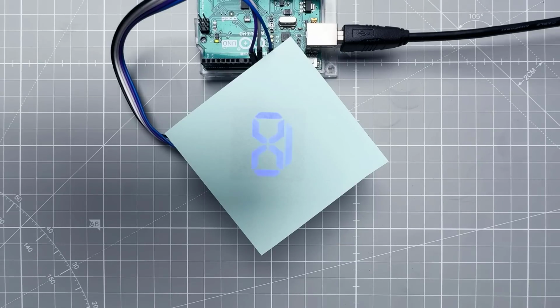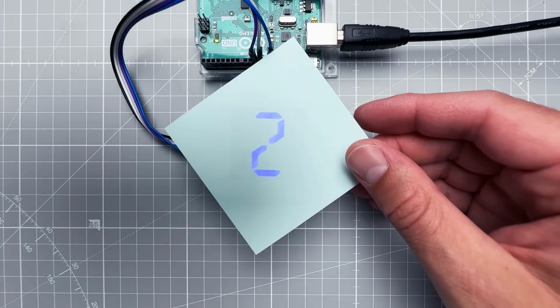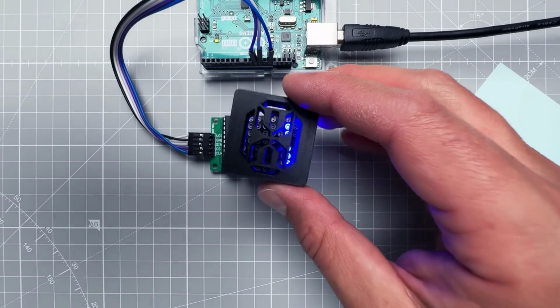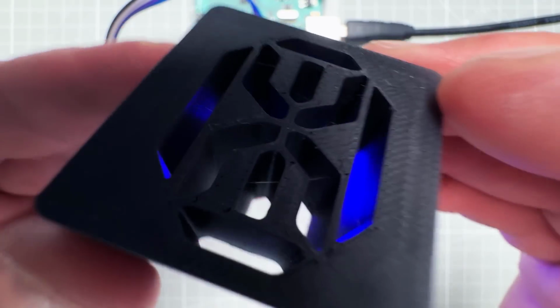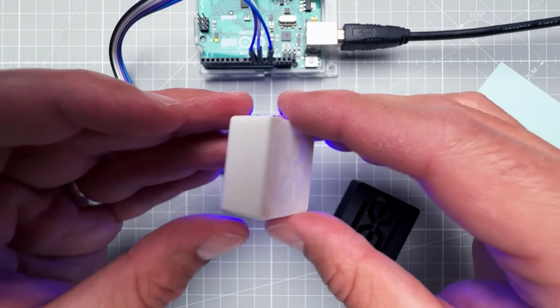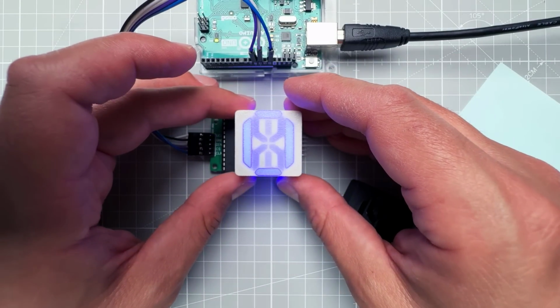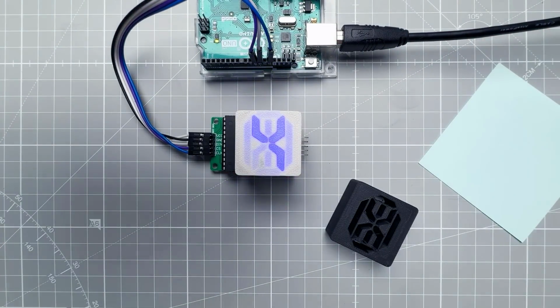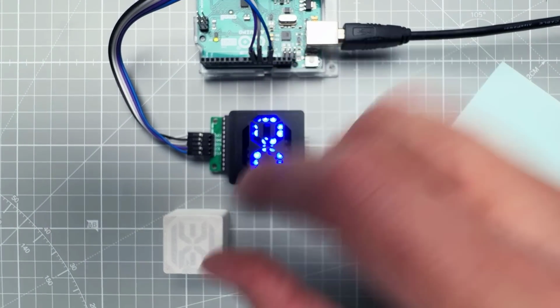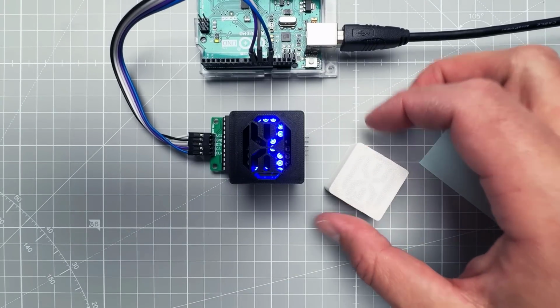That filament is slightly translucent, so if we only print one layer, it should be transparent enough to act like a diffuser. By the way, the reason why we don't print everything in the white PLA material is exactly the same. The walls between those segments are quite thin, so some light might be bleeding between those segments if we use the white PLA. You can see that with the white 3D print, even the segments which shouldn't be lit are slightly shining. So let's use black PLA for the 3D print and add one more layer in the white PLA, and for that we need to go back into the Fusion.